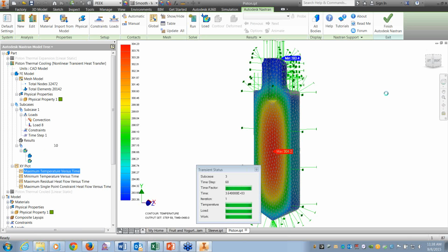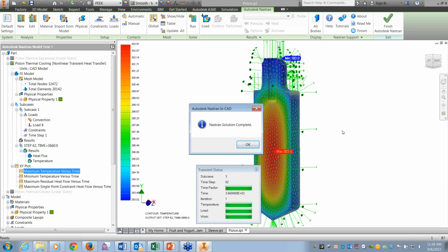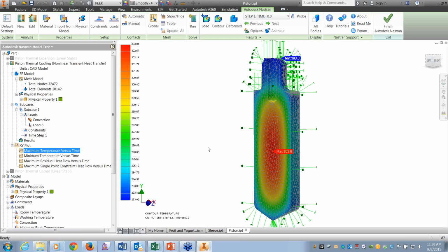You might find that here this plunger has a small threaded portion up towards the top and screws onto a rod that's coming down. Well, maybe to cool this down quicker so that you're not wasting time waiting, you want to run that threaded rod down further into the piece, or even just run a portion into it there as a heat sink. So while I was babbling on there, the analysis finished.